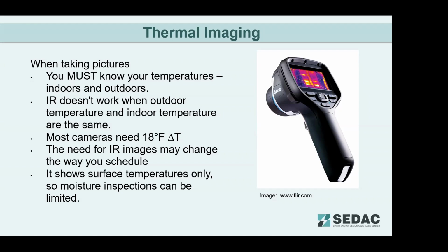If it's 70 degrees outside and the sun is out and it's the afternoon and the attic temperature might be 120, 130, I can use the camera on the ceiling and probably see some problems. But on the same day, I wouldn't be able to use it for the walls. So knowing that temperature is massively, massively important.